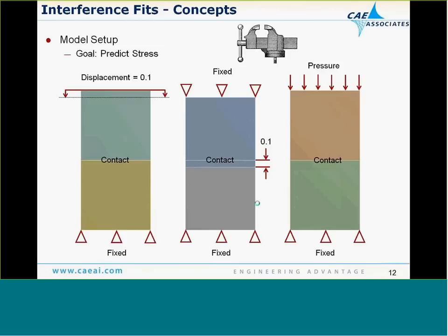So if we just look at a problem here where penetration is important, and cases where it might not be important. Let's just say, for instance, we have a couple blocks that we're modeling here. And those two blocks, we put those in a vise and then just crank up on the vise and displace at 0.1, some amount of displacement. So we start off and then squeeze these together. We could simulate this, and we'd have some contact in between these two parts. So this is one way we could set up and solve this problem.